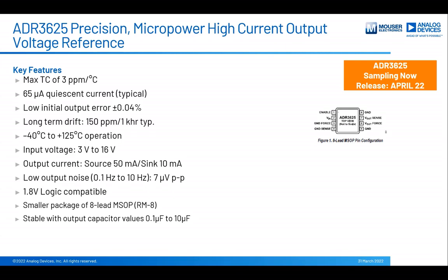It has the combined function of a reference and an LDO. It has high reliability and lifetime accuracy, and unlike LDOs, the quiescent current stays the same when the load increases. It also has low thermal hysteresis, making it ideal for low power applications.